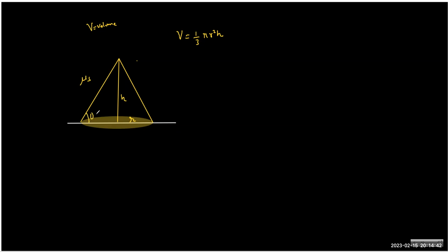And if the grain has a coefficient of static friction mu s, then it will stop at an angle which is exactly equal to the repose angle. So the moment it reaches the repose angle, it will stop. It will not fall further. It will maintain this cone shape, assuming you're pouring really slow. Those things are taken into consideration for the assumption.